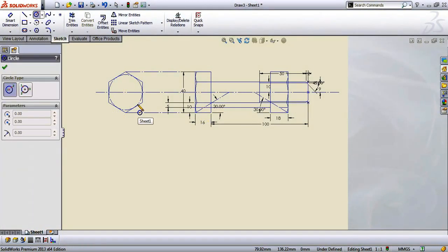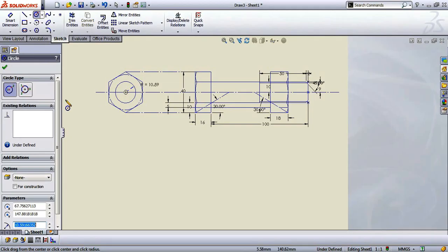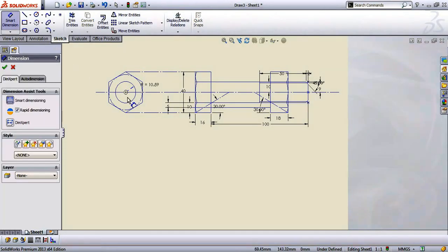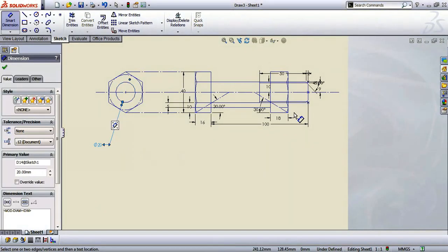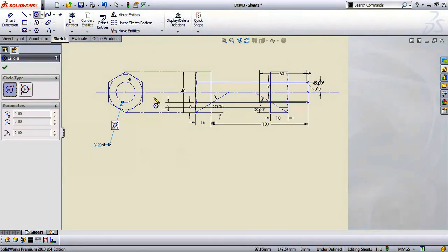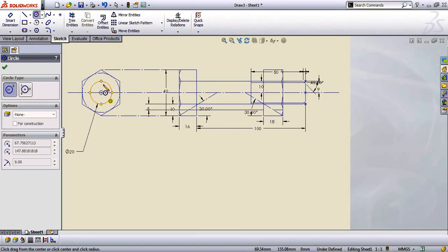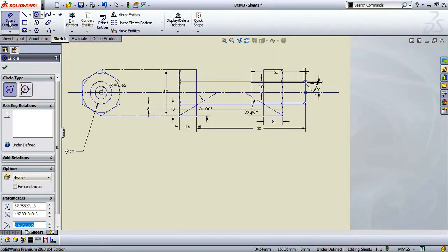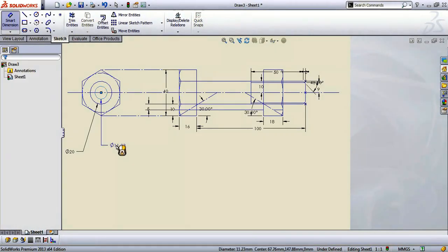Now, inside this, we are drawing a circle of the nominal diameter. The nominal diameter is 20 mm, as given. On the right side view you are seeing, we can even see the particular chamfering on the thread also. So that will be around 18 mm diameter.